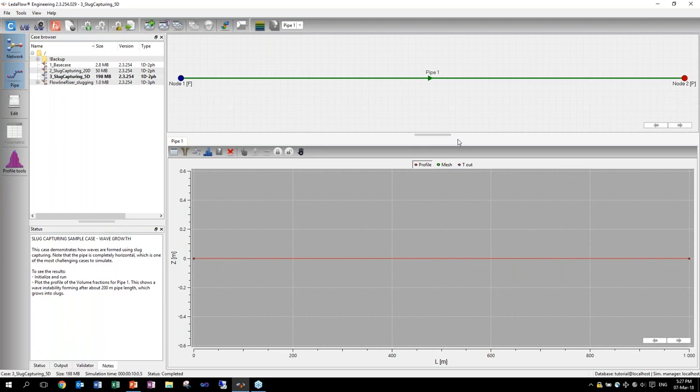Did we achieve mesh size independence with 5D cell size? Not really better, but do you want to just mention something on that? Yeah, for this particular case, I didn't try that. But we might. But as I showed in the presentation, this ill-posedness makes it a bit tricky to prove the mesh independence, because we know that there will be some unphysical waves appearing if you go to a smaller cell size anyway.